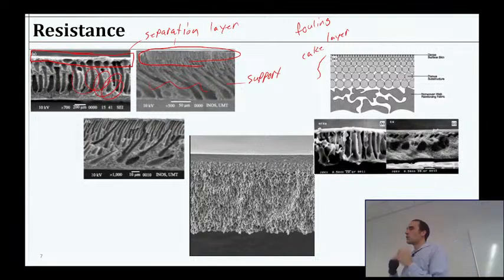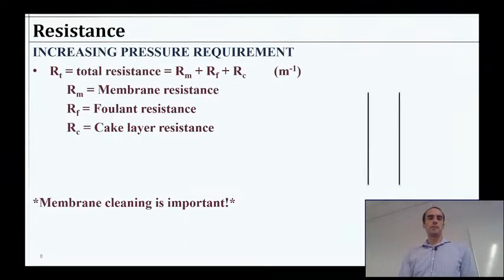A lot of times it's going to be just a quick little reversal of our pressure to just backwash it like that. So there will often be routine, quick back flushing or vibrational energy, something to try to shake off the dirt during operation and let it go out the retentate. And then maybe after some days or weeks or some amount of time, a more hardcore cleaning for the filter, depending on the application. Okay, so let's talk about that resistance.